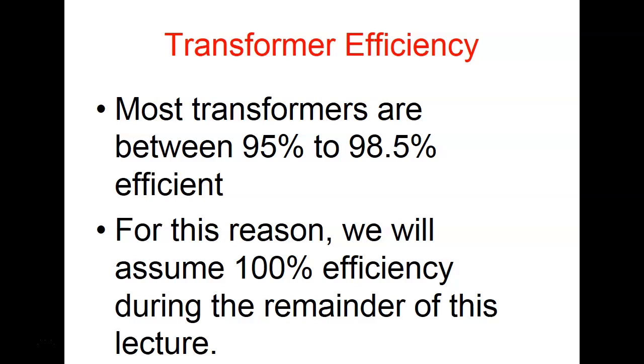So for this reason, Alabama Power would really have to worry about power supply efficiency, right? Because they go through a lot of power, a lot of substations getting that from up there to down here. And every time you go through a transformer, you're going to lose a little efficiency, and you're going to have losses in the line. So even your power line transformer usually has 3 taps on the primary side. So the guy that's wiring it can move it between 3 taps and get you close to 120 and 240. But actually, NEC says it's got to be within plus or minus 10% and still be considered good, right? Does that make sense?